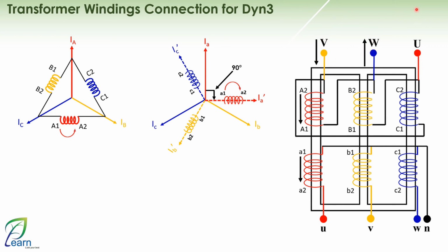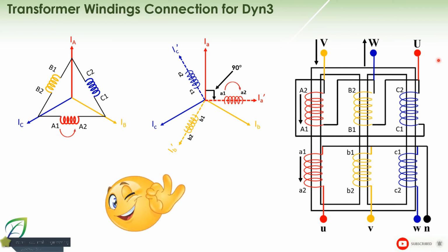It didn't actually draw current from the red phase cable, but here, just to be clear, on this point, the current, as it is drawn from the red phase in the star, is drawn from the red phase in the delta as a winding, but as external terminals from the transformer due to this vector group, it is drawn here from the yellow and blue phases. Pay attention to this information. It will be very useful when we later discuss vector group compensation in numerical relays, because I will notice here that this current is matched by a current in two completely different phases that have nothing to do with the red phase. So how will the relay handle this and process it internally?